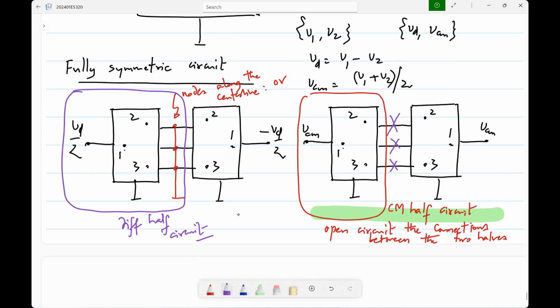So ideally, in a fully differential circuit, everywhere you should have a signal and its opposite in the counterpart. Okay, voltages or currents. That means that necessarily the average value or the common mode value will be 0. But that has to be enforced through a separate feedback loop that is called common mode feedback. Okay. So now we will need to introduce, first of all, we have to turn our op-amps into fully differential topologies.